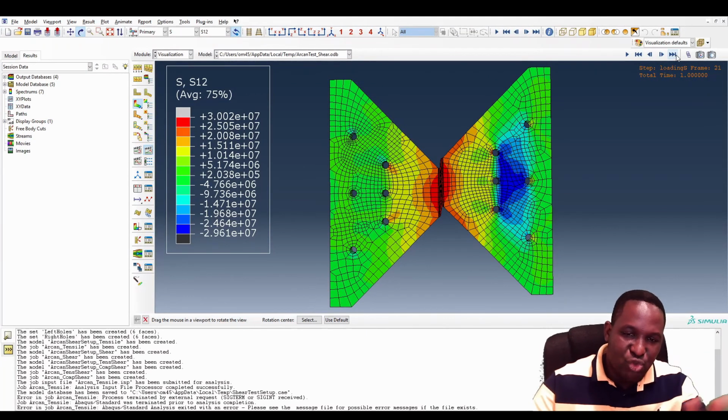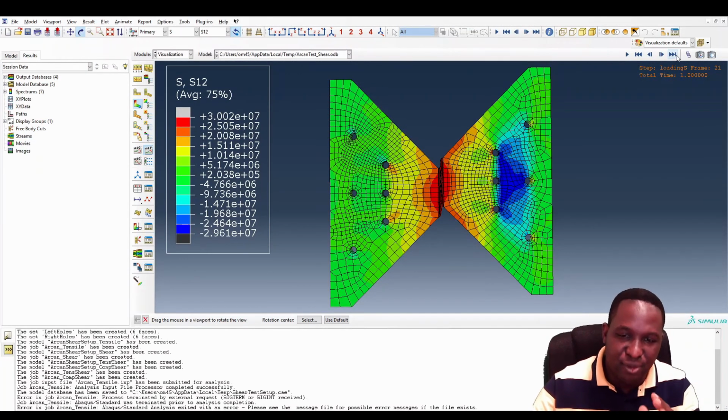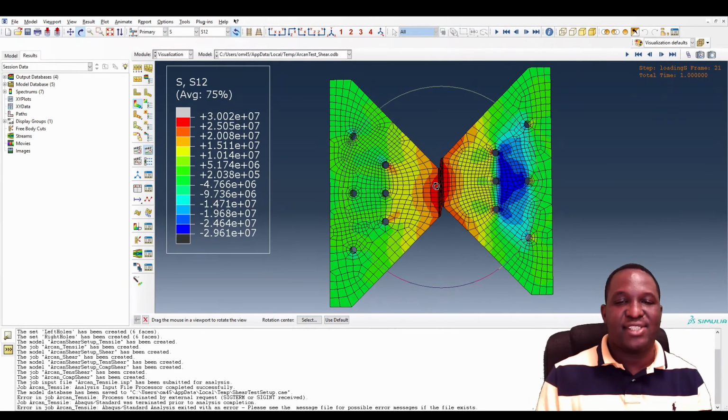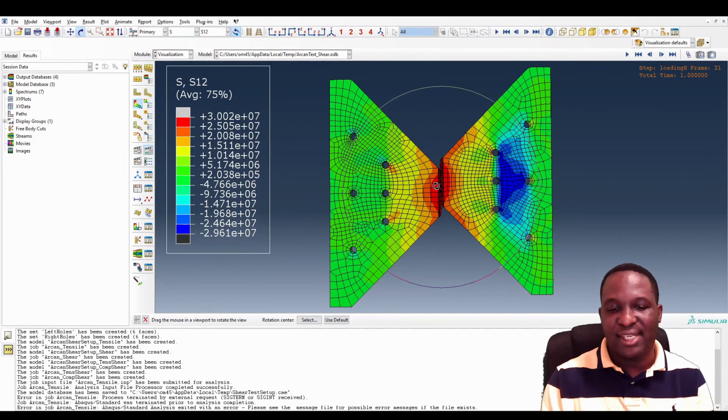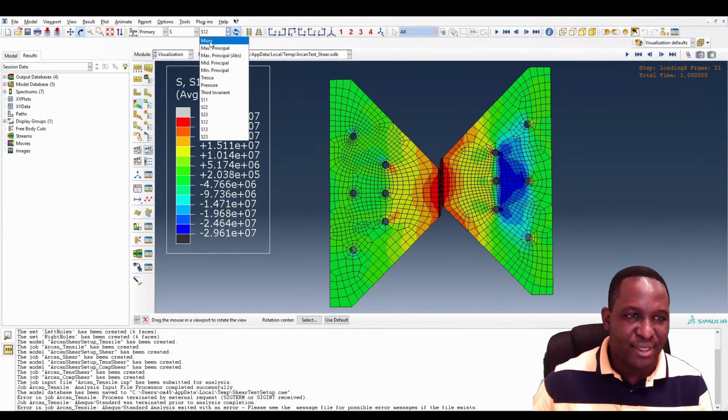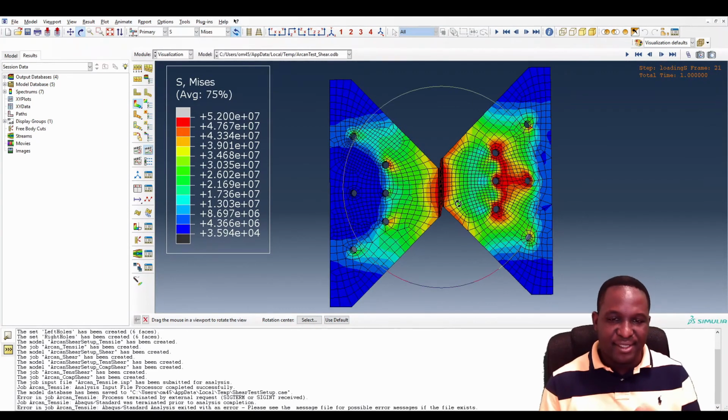By constraining the material in the way we have done, we're able to enforce a shear deformation concentrating in the middle. So that means if we extract the history of stress in that node section, it is actually a history of shear, in-plane shear for this material. So if we look at the von Mises stress, again, it's a different display.